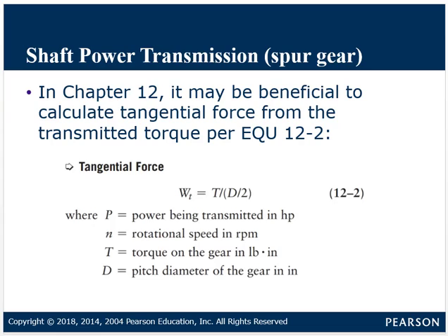Now, we're going to use a different equation in Chapter 12 to calculate what the tangential force is, because in Chapter 12 we typically have the torque in the shaft. We'll calculate the torque first based on how much power we're going to be transmitting, and then we'll convert that into the tangential force. So this is going to be equation 12.2.